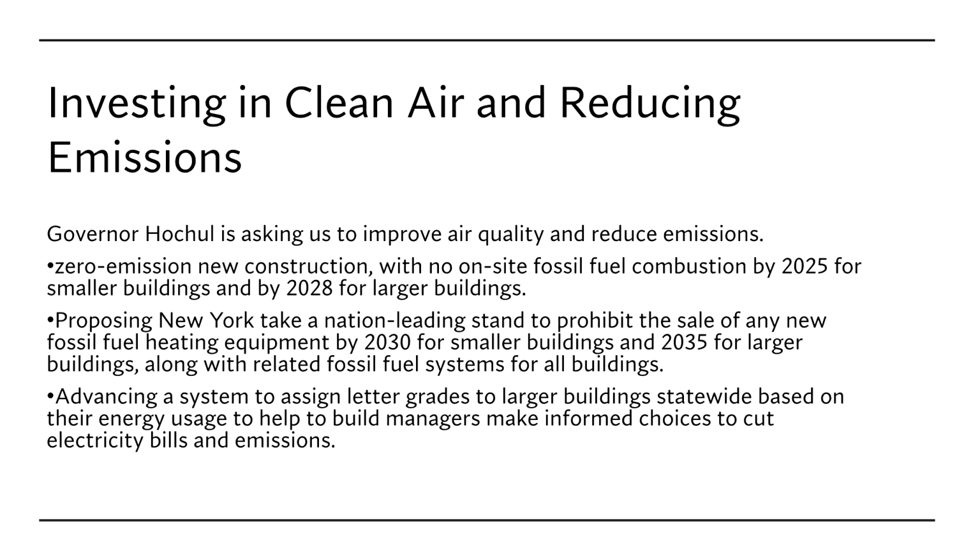And in order to do that, we mix apples and oranges to come up with that number, where the coefficient of performance is BTU out divided by BTUs per hour in. That is the true mathematical equation of how to do things. With the SEER ratings, we're providing the output in BTUs and our input in watts, so we wind up having 2 different numbers. Not a very good engineering approach, let's put it that way. All right, anyway, so that's my kick on efficiency.